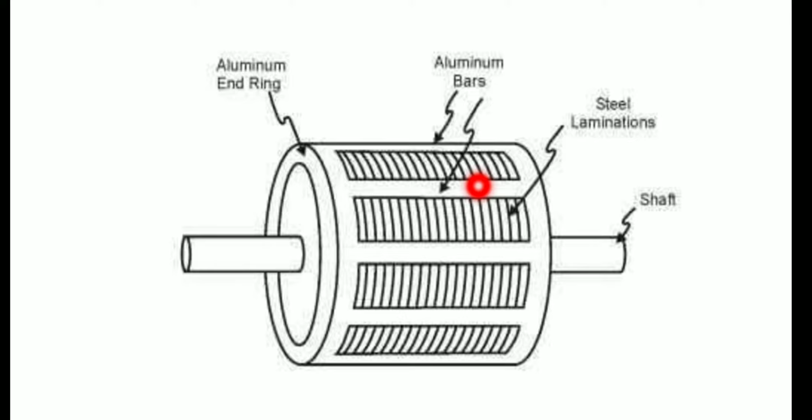According to Faraday's laws of electromagnetic induction, whenever there is a change in the flux, only then does EMF get induced in the circuit. Due to this rotating magnetic field, there will be an induced EMF, and due to this induced EMF, flux is produced inside. That flux is called the stator flux. This stator flux travels through the air gap and then cuts the rotor. Is it right?